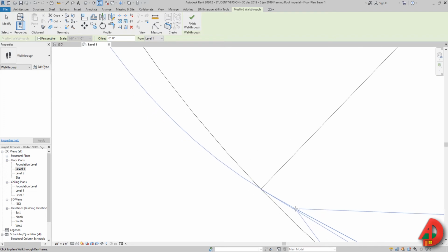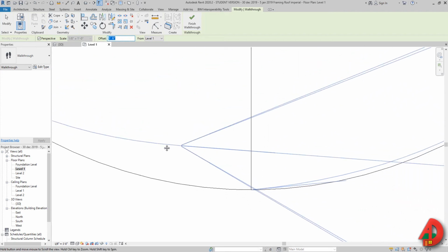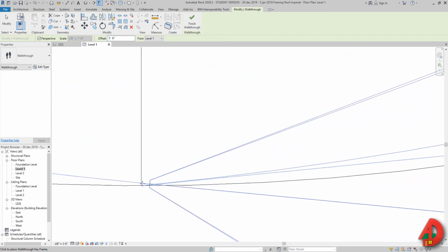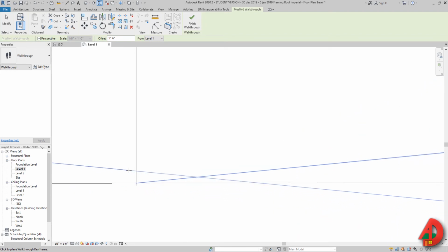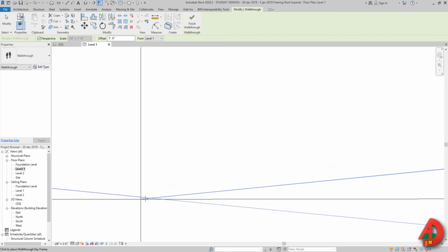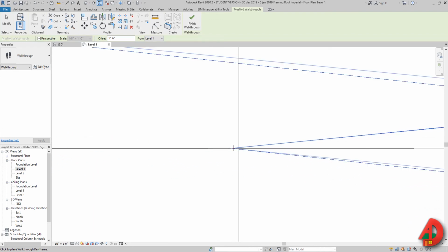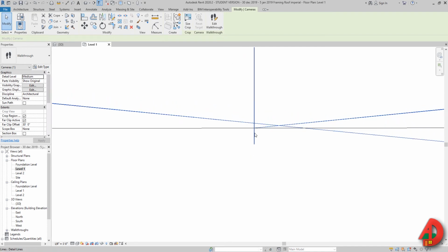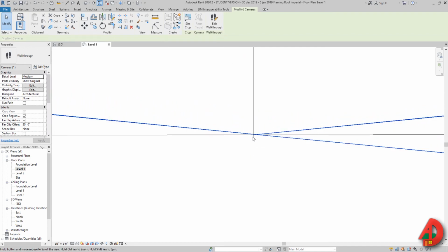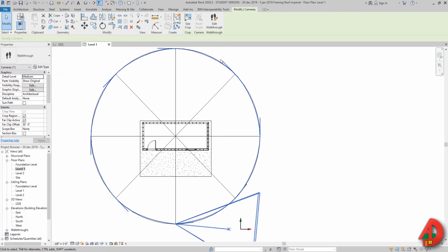And for the last one, if you guys remember, we started with the eye elevation of 5 feet and 6 inches. And like I said, try to zoom in as much as you can and match it with this starting point. And I'm gonna press right here. Now I'm gonna press escape on the keyboard and double click on the scroll mouse and this is gonna be a walkthrough.